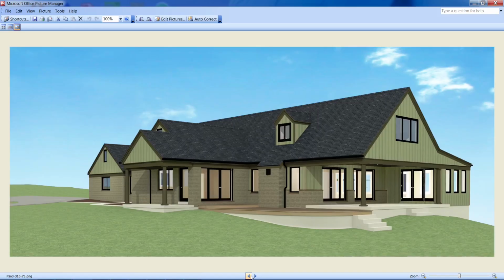And then we come over here, and once I arrived at that, it was enough for this film, because there was still a lot to discuss, both in terms of the style and what's represented, and some other ideas I have in mind. This rear roof pitch, if we keep this room at 8'0" finished, this can be 2/12, which can be covered with the ice and water shield, and the shingle warranty will still carry on that pitch. But if this room goes higher, we're not going to have room to keep that at 2/12 because of the dormers on that back side.